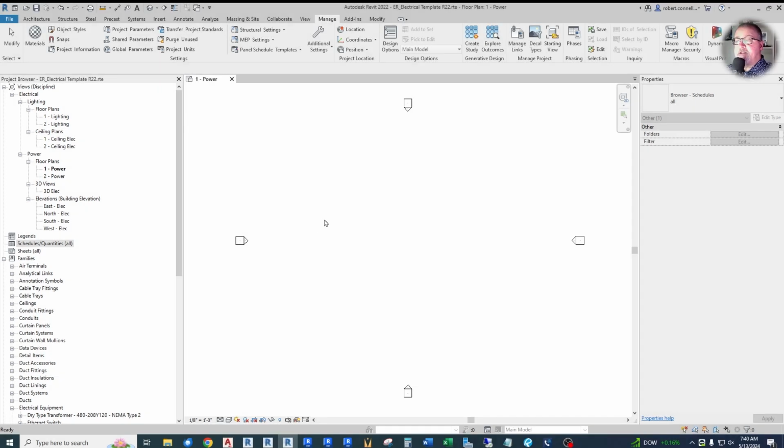One of the first things I like to do is create what's called a starting view. If you look at some of my other videos, you'll see that when I open a project, I end up with a starting view that is not just a floor plan or even a very detailed 3D view, things like that. You want to open up your project in a simple to render type of view. Otherwise, you can end up waiting 10 minutes for this thing to open up to the 3D view. Also, this starting view can have some information about the project. So let's see what I'm talking about. A starting view is actually a sheet.